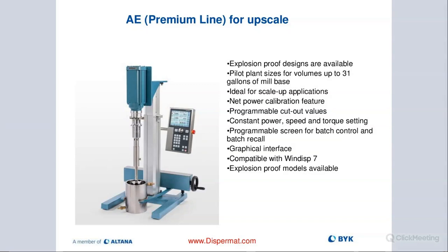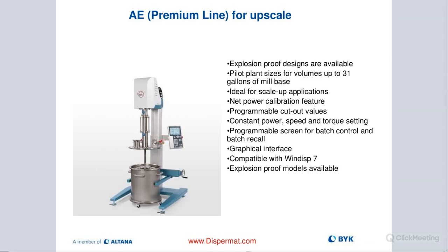It's really critical in all the machines, but on the small ones, where a lot of people like to operate without a cover, this is really a safety concern. So the threshold setting is very, very important. On the larger machines, you can see they come with a cover. It can also be dangerous if you run it without a cover, but because it's closed, you're unlikely to have a spinning blade outside of the container. And then the same threshold setting for the bottom, H2 we call it,